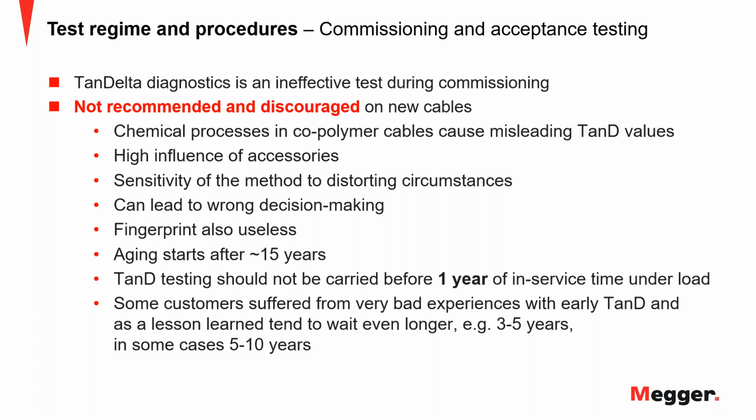So, the time to call a cable an aged cable, we're talking something around 15 years here, approximately, as a rule of thumb. Now, before that, the cable shows a different dielectric behavior as well that has nothing to do with aging. It's simply chemical processes, because you have inhibitors in there and additives, acetone and all of these things to prevent the water trees from forming and growing. And that has a significant influence on the dielectric behavior.